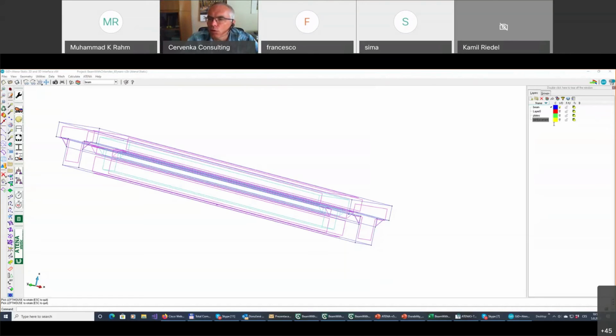We don't have any corrosion model for steel beams. So you could do that, but you would have to consider the reduction of steel in the steel elements directly, by reducing Young's modulus or the area or strength of the steel beams, let's say manually.